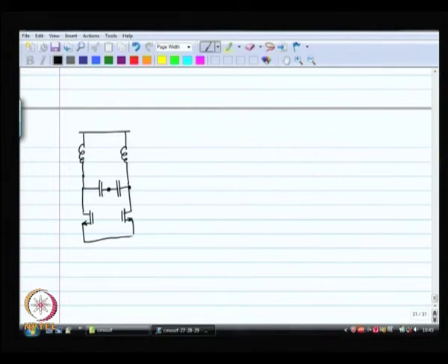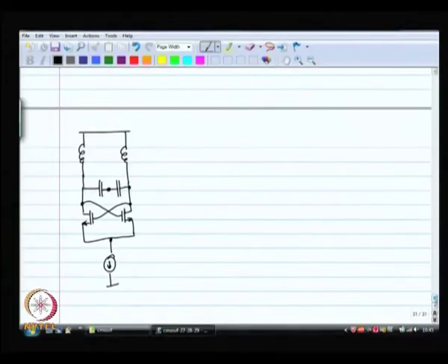So, this is a negative resistance based oscillator. I have got a tank and I have got a negative resistor to compensate for the tank loss. Basically the loss is in the inductor. To compensate for that I have built a negative resistor, and when the negative conductance is more than the positive conductance of the tank, then oscillations win and my poles go into the right half side of the S plane, which means that I get oscillations.